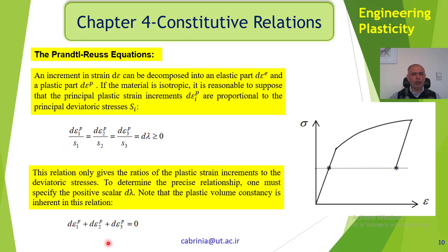This can be proven if you put volume equal to constant and take a cubic element, a parallelepiped, with the sides A, B, and C, and calculate the volume, and then write these epsilon 1, epsilon 2, epsilon 3 after the cube is deformed into, for instance, sides A plus delta A, B plus delta B, C plus delta C. Obviously, delta B and delta C could be minus.